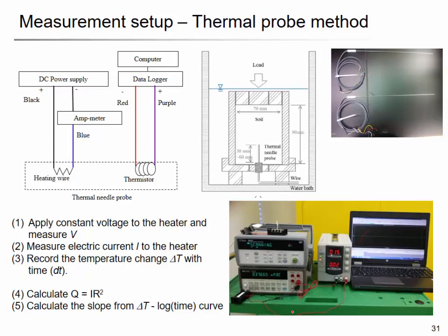Yes. High conductive means that it can flow the heat easily. So for a given heat flux, it will pass the heat. The energy will just flow. So the temperature increase rate will actually be low. You can think of the opposite way. If you insulate it with maybe a cotton ball, it has very low conductivity, then heat cannot escape. The heat will be trapped inside, so you have a very high increase in temperature. Temperature will rise very fast.